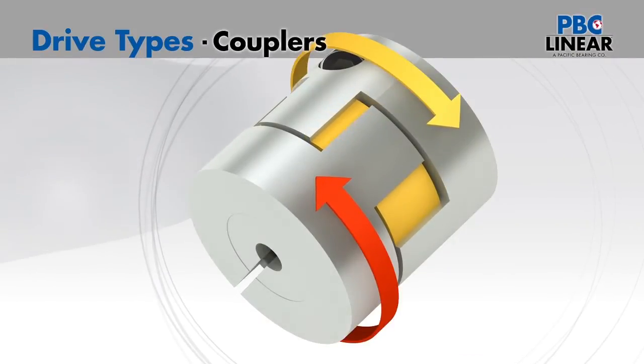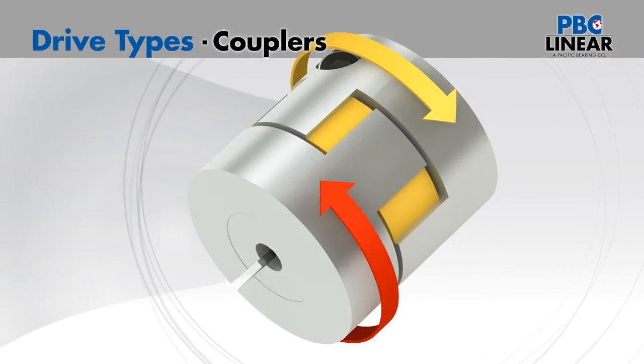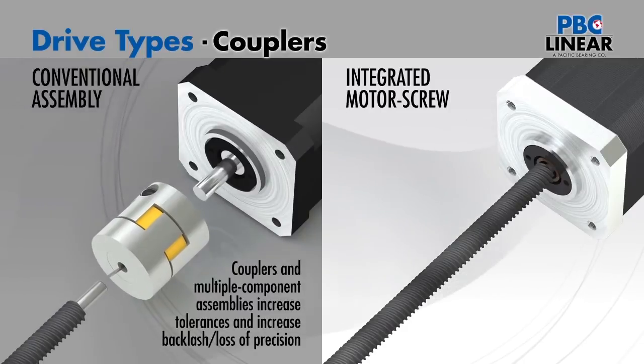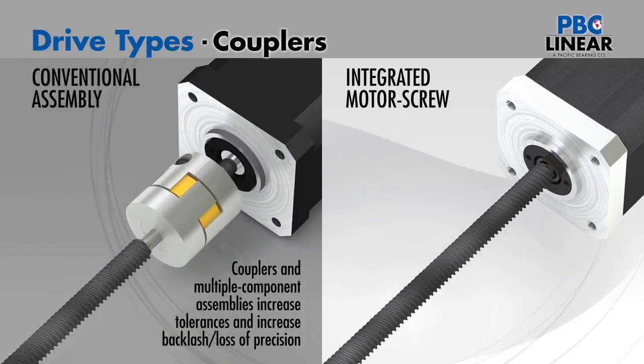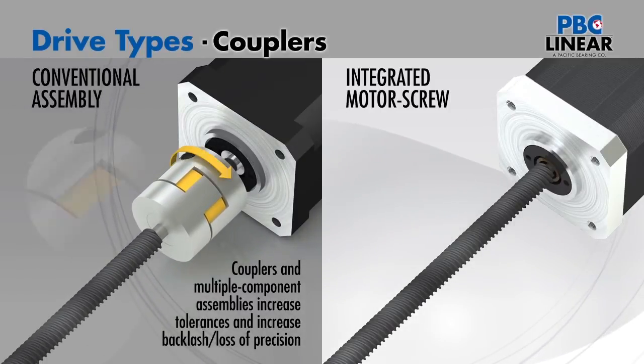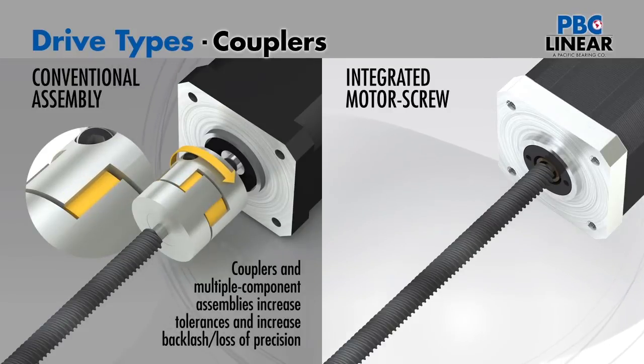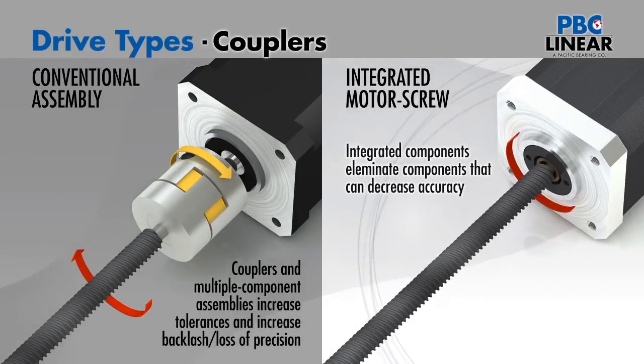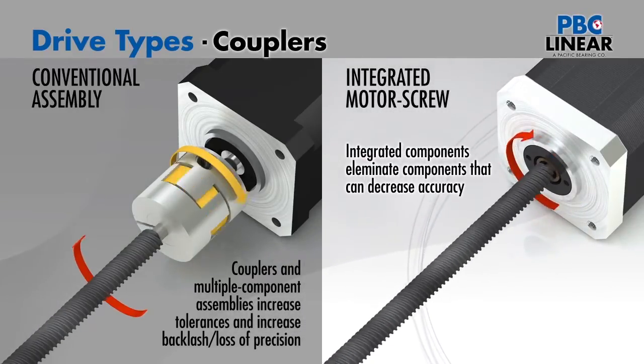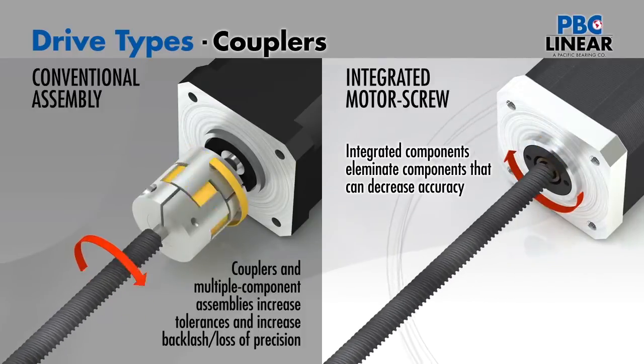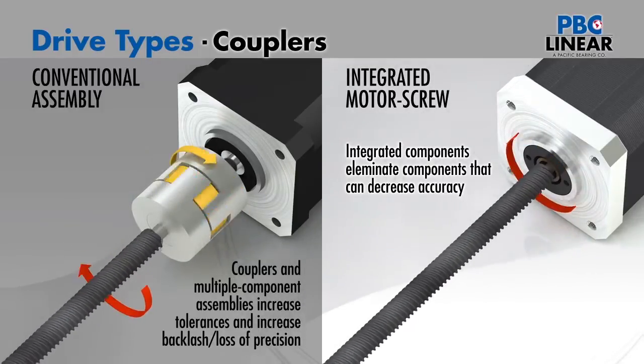An additional mechanical component in the system often taken for granted is the coupler. Transferring the power from the motor to the screw or drive pulley, this simple item is also subject to backlash that will ultimately have an impact on the positional repeatability of the entire system. If there is a gearbox in between, this is also an item where backlash needs to be considered.